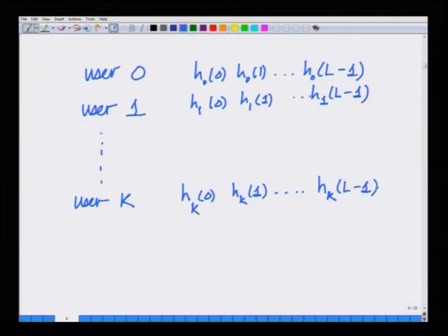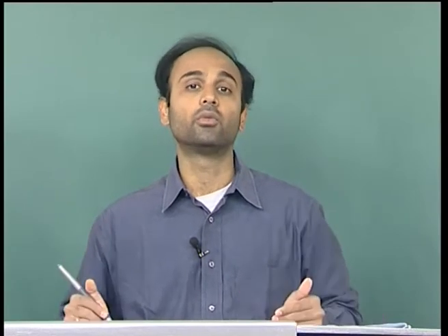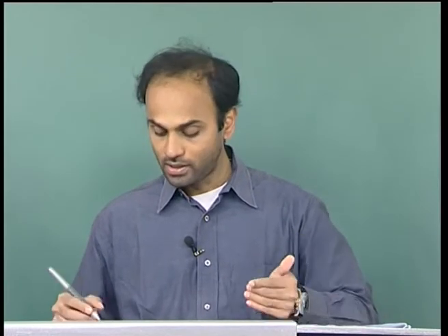Previously in the downlink, where we were analyzing the received signal at user 0, we had only one channel, that is H0 corresponding to user 0. Now, because of the uplink, each user signal is traveling through his own channel, so there are K different channels, that is H0, H1 up to H subscript K. So, there are K plus 1. In fact, considering 0 as the desired user and 1 to capital K as the interfering users, there are now a total of capital K plus 1 different channels through which these signals are propagating. Hence, everything essentially remains the same.